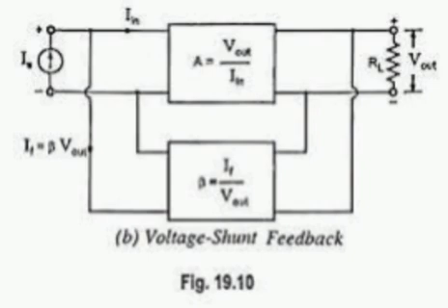If small rd tends to infinity, then AV equals minus GM capital RD, that is the numerator part, by 1 plus GM RS. So AV equals minus GM RD by (1 plus GM RS). If RS equals 0, then AV equals minus GM RD, where AV means voltage gain.